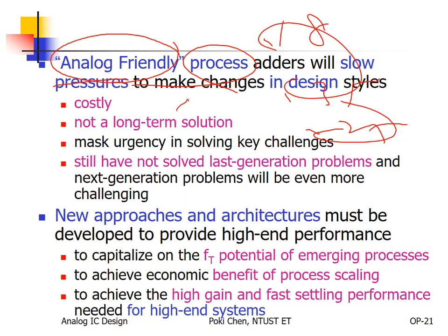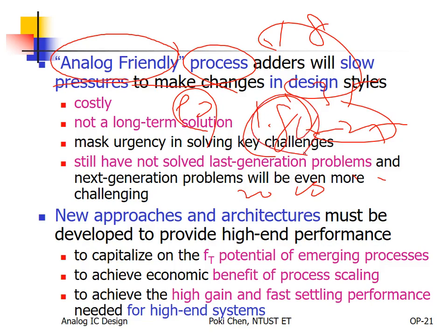If you apply analog friendly devices on new processes, wow, what does it mean? Hey, for your 19 nanometer, or even I guess for 20, 28 nanometer, they still can provide some transistors, functional under 1.8 or even higher supply voltage. Okay, but for the size, for 1.8 volt MOSFET, the size I guess is about the same as 0.80 micron, right?